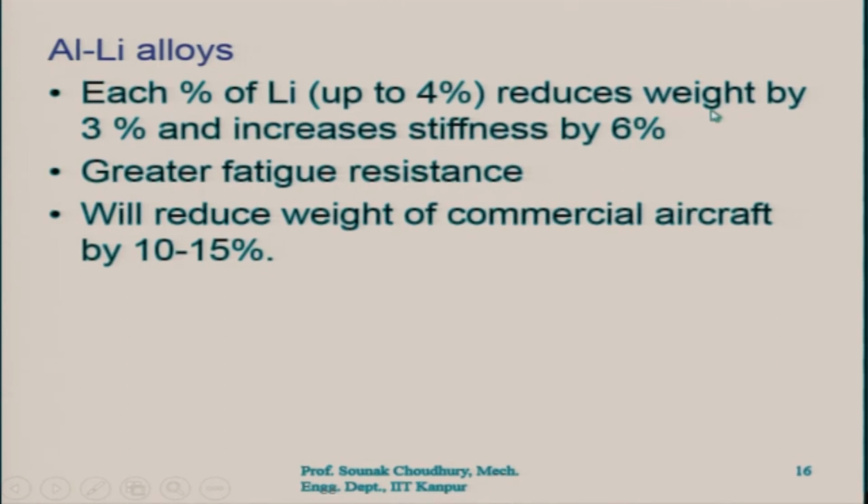Both these characteristics, the reduced weight and the increased stiffness, are desirable in engineering materials and engineering parts. So, the role of lithium is great in the case of aluminum alloys, and that has been found out by research. Greater fatigue resistance. Repetitive loads can be withstood by such alloys, aluminum lithium alloys.